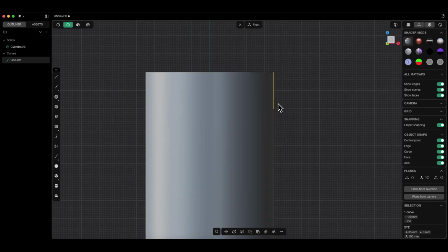This line is a construction line. Now let's create another line. Again, use Shift+A to start the line drawing command. Click this point to begin. Drag the cursor to the right and enter 25 mm for the length. And if you click once with the left mouse button instead of pressing Enter, the line will be drawn and the command will remain active. Now drag the cursor downward.